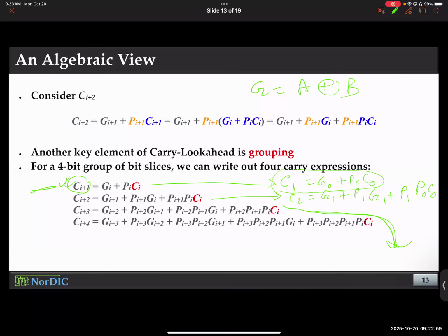And when do you think A and B are available? At the start of the operation. You don't have to wait on A and B. You begin with A and B, basically. You already know A and B. So you directly calculate G0. So when you try to get G0, you do A0 XOR B0. What is 0? 0th bit. When you try to get G1, that's the first bit. G2, that's the second bit. But you can do a bitwise XOR. Yes.